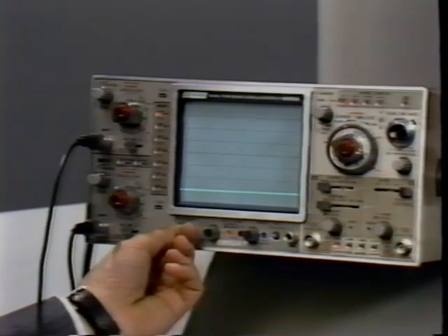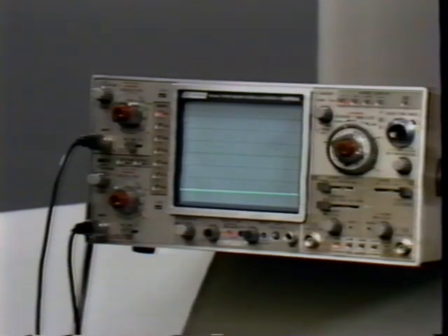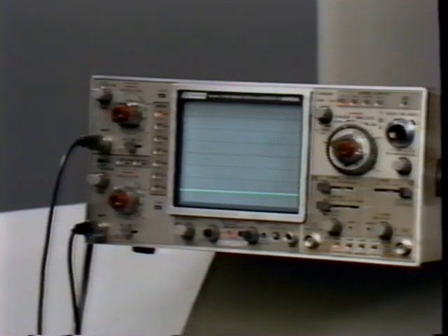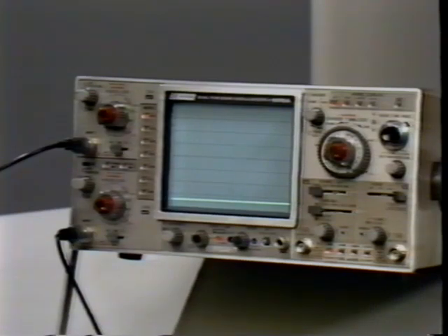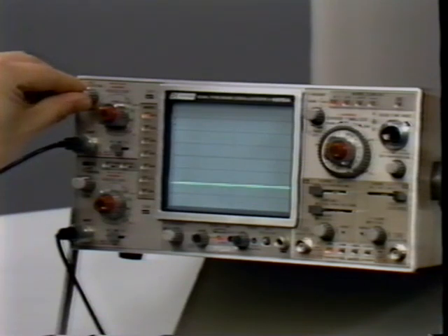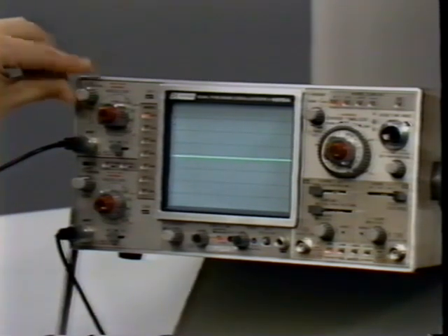Also, adjust the focus and intensity controls for a sharp line that is bright enough to read but no brighter. Focus will allow you to make a more accurate reading. Excessive brightness can cause small details of the signal to be lost, as well as burning the phosphor coating of the tube. Never leave your scope displaying an excessively bright signal for long periods of time. When observing digital signals, use the bottom of the screen. When measuring AC inputs, the center line is usually best.